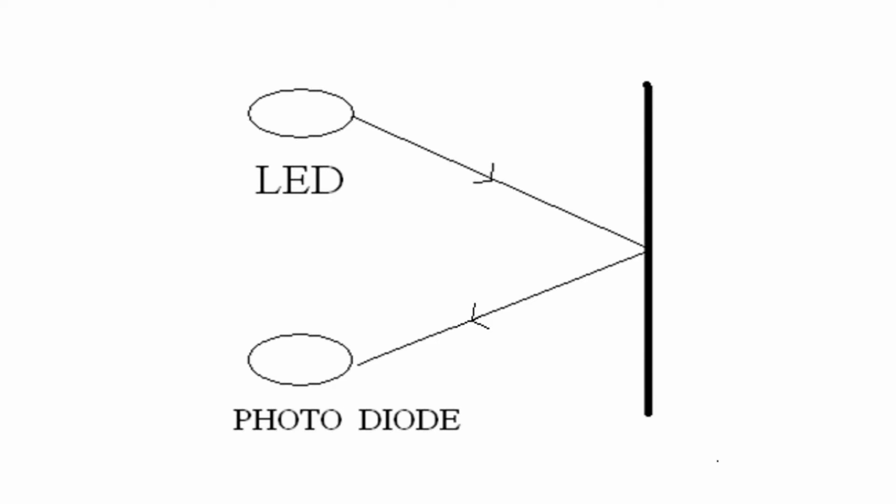In fact, the range can also be tuned. But at maximum it will go up to 4 to 5 centimeter, not more than that, because light beyond that will mix up with the environment light. So if you use that, probably in night time this sensor might give somewhat better range compared to daytime. In daytime it will mix up with the environment light and it will not fall back.